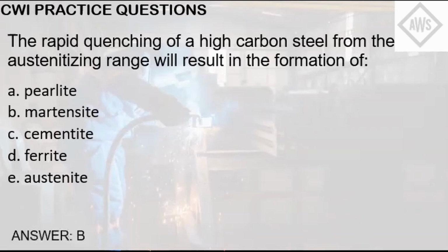martensite. Martensite exhibits a body-centered tetragonal structure which has high internal energy, resulting in high hardness and tensile strength, but comes with low ductility and toughness. For the choices, pearlite forms at a slower cooling rate than bainite and martensite. Bainite forms at a slower cooling rate than martensite, hence with lower ductility than pearlite. One characteristic of bainite is that it is very difficult to see under the microscope.